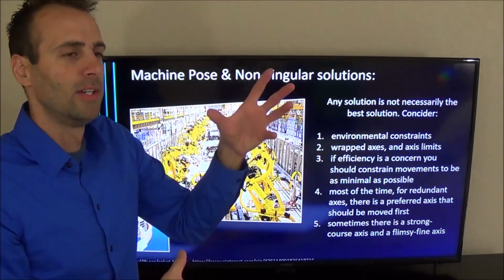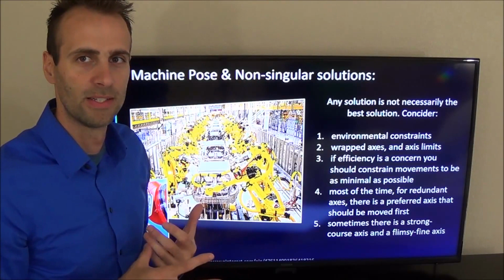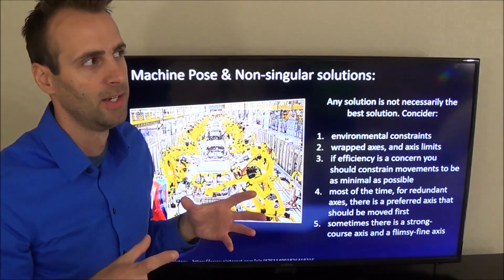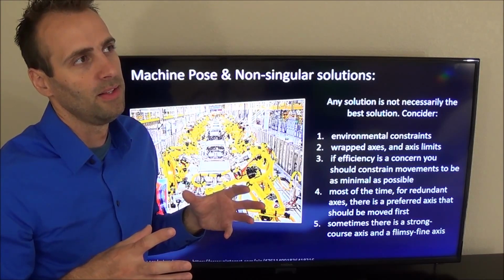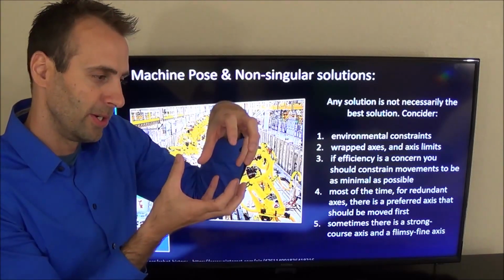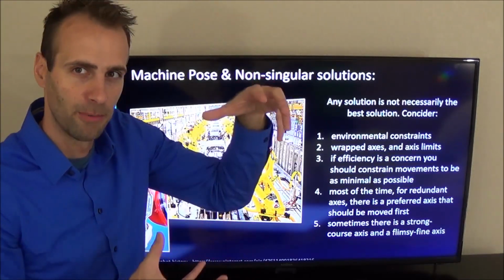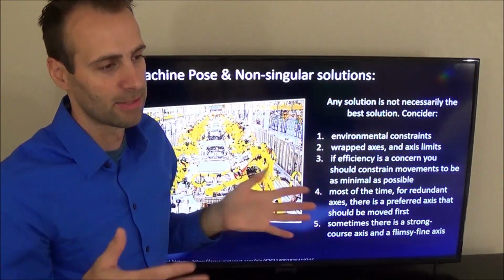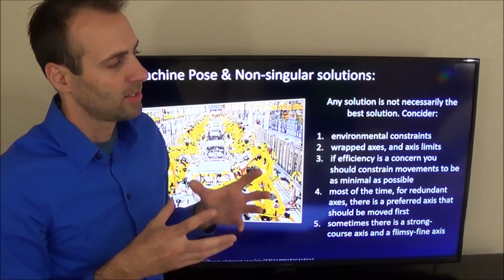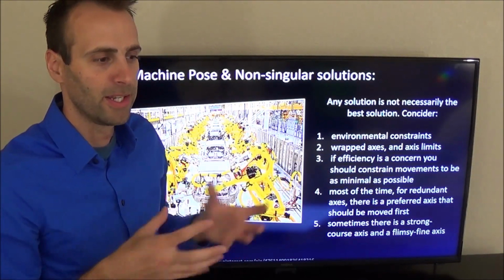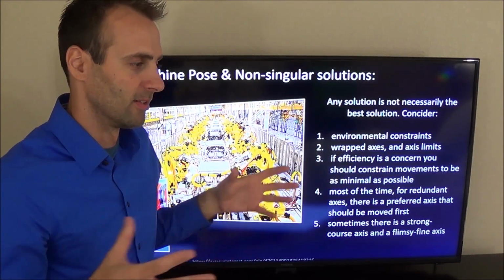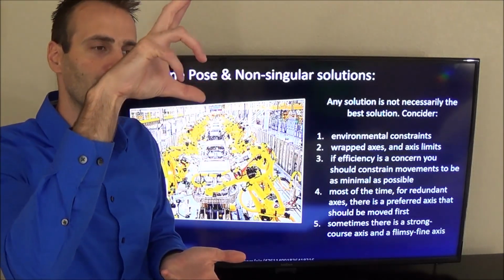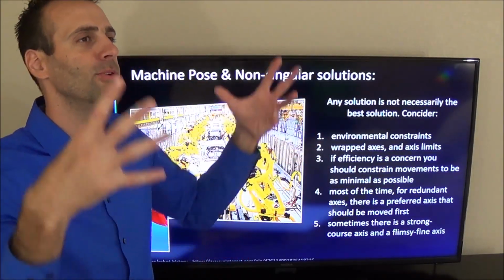On the knee mill, in the previous example, or really big CNC centers, there's only so much motion that you want to do in your precision axes. The longer the axis, the less precision you're going to have. So what they do is, if I'm milling a big tall part, I want to move my precision axis up. I want to physically move that whole thing.